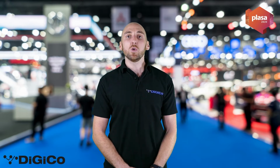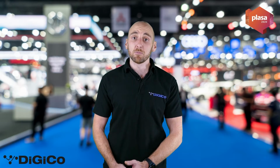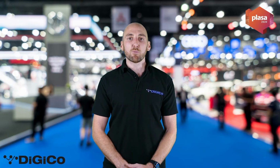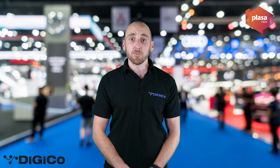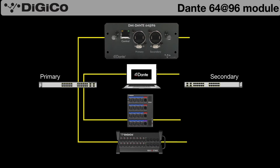On the card are 2 RJ45 network ports to allow for redundant connection of a system. All DiGiCo Dante products support network redundancy. A redundant setup sends 2 copies of all of the Dante information, audio, clock, data, control messages, etc. across 2 separate networks. So that should one network fail for any reason, maybe due to a broken cable or a power outage, then audio will not stop flowing through the system.